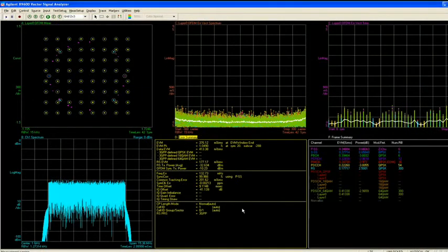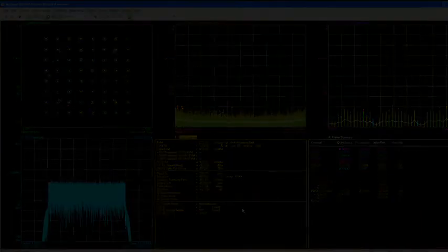Being the most basic measure of modulation quality, composite EVM is an initial step to investigating transmitter quality. From here, you can investigate more detailed MIMO characteristics, such as time alignment or power characteristics between transmitter branches.